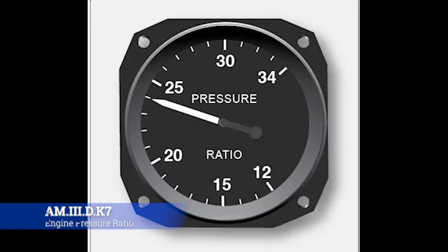And it's used by the pilots to monitor engine power settings during flight. In a lot of ways, it serves the same thing as your RPM gauge whenever you're flying a recip engine. If you're saying, hey, look, I want to set at 2,000 RPM, you might say, hey, look, I need to set our pressure ratio up to 20 or 25, or whatever. It's real common in older jet engines and some modern turbofans as a primary performance indicator.